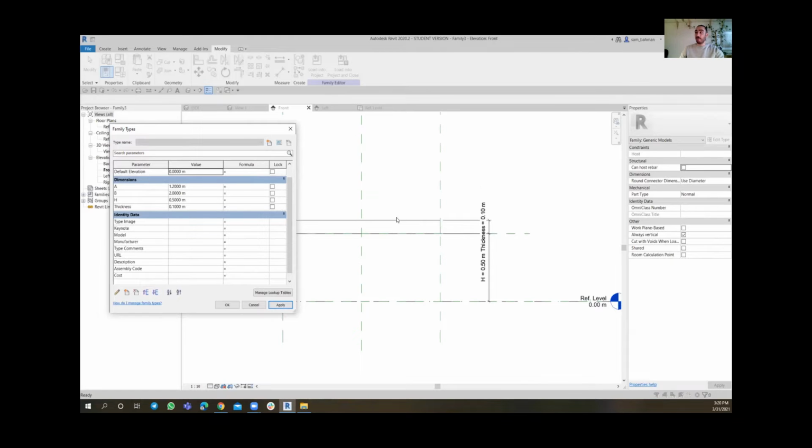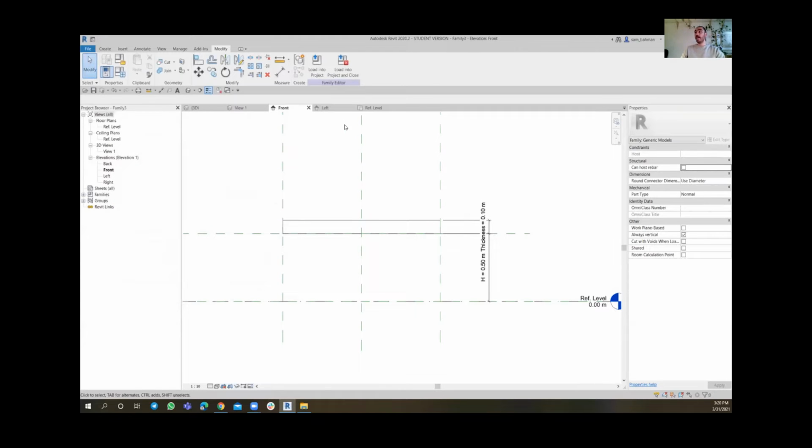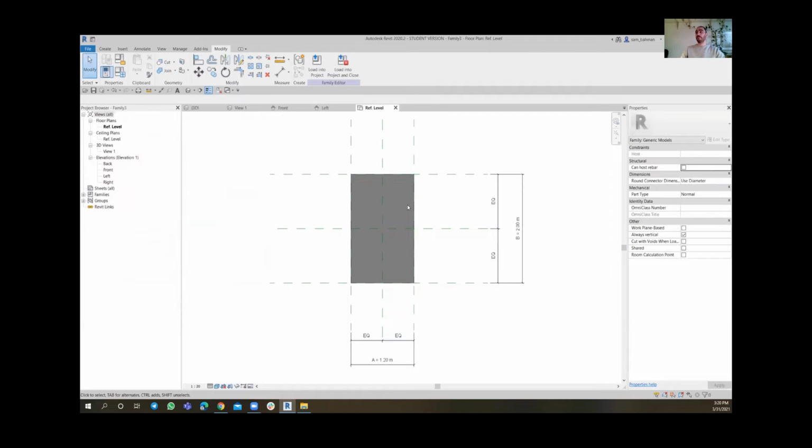However, the thickness of the table is not getting changed, which is the purpose, the aim of, let's say, parametric modeling. If you have set up the parameters in a proper way, then you don't need to be worried about changing these parameters, because nothing else happens. Everything would be in proper order. So whatever value we put on the height, we still have the peace of mind that the thickness is not getting changed unless we change the value, right? So gonna click on apply, gonna click on OK, and again, I'm gonna get back to the ref level.